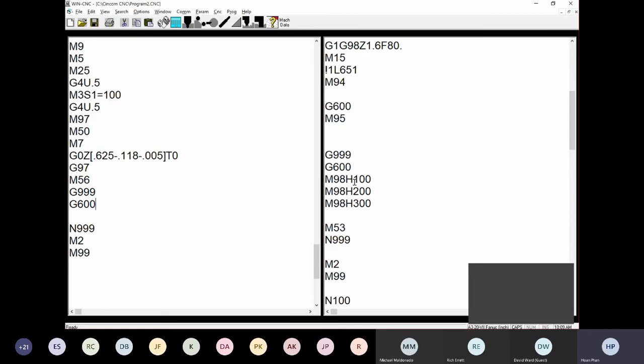If you don't retract the material, when you call the T51 or T52 on the sub spindle, it will come over and smack on the material. So this way, I will put a waiting code right here for number 1, L, and then whatever number you want to put, you put in here. Okay, 515, something like that.